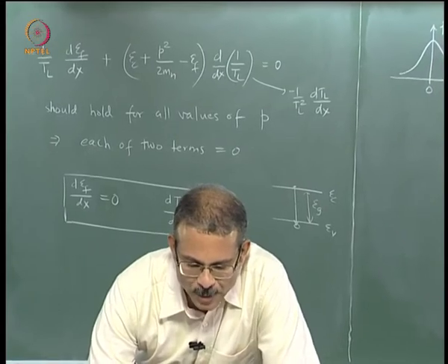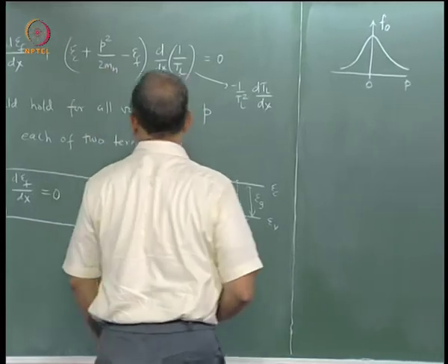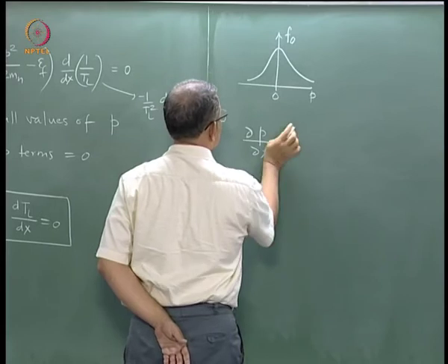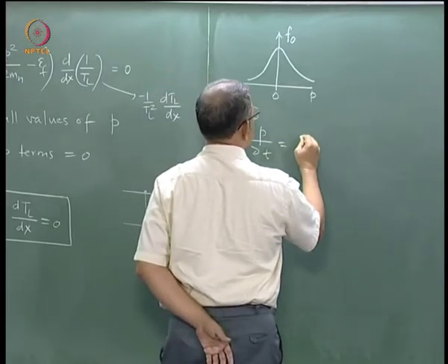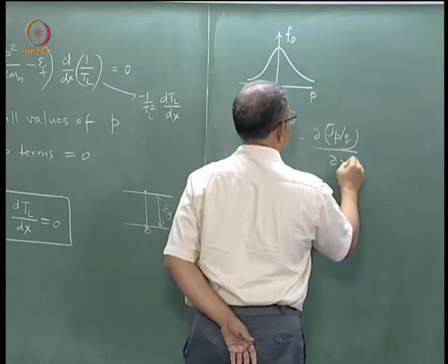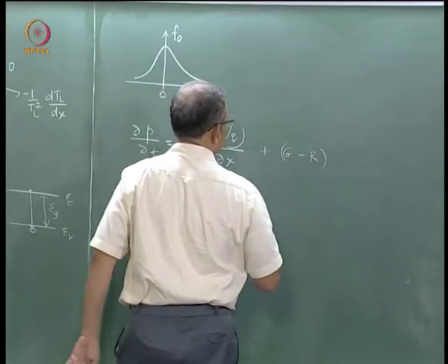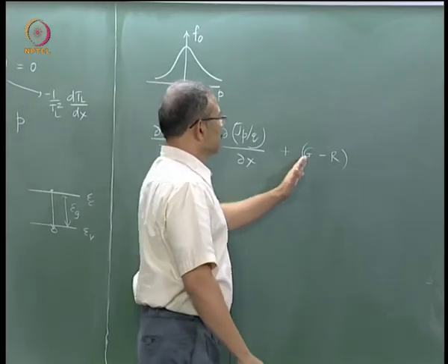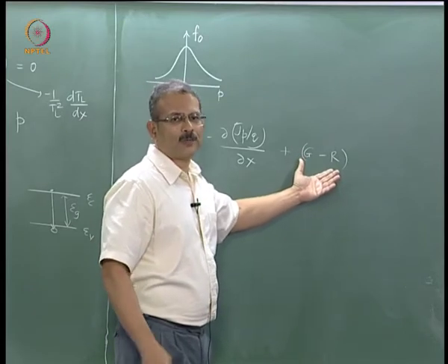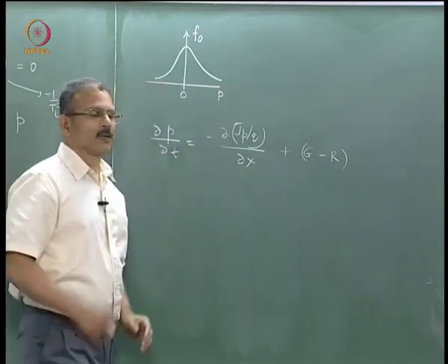Now let us show the correspondence of this equation with the hole continuity equation. Now here we are writing the term G minus R because the net generation or recombination for holes and electrons would be equal, because the processes are always balanced, right.